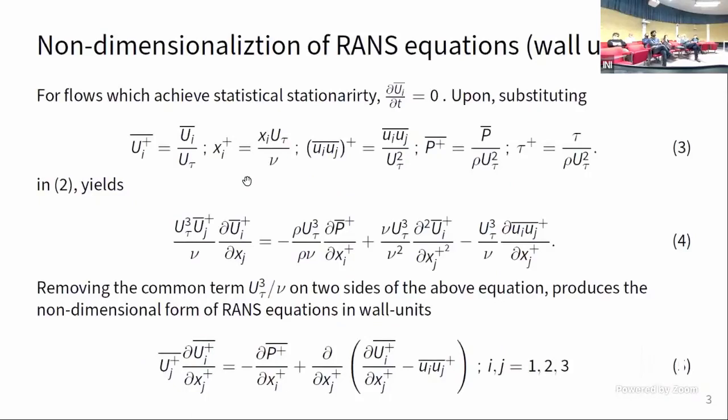In this case, I'm just going to be non-dimensionalizing with u tau and viscosity. The reason I'm non-dimensionalizing is because at some point I'm going to be introducing a fractional derivative, and then it would not be consistent dimensionally speaking, because the fractional derivative will give you a quantity that is dimensionally inconsistent.